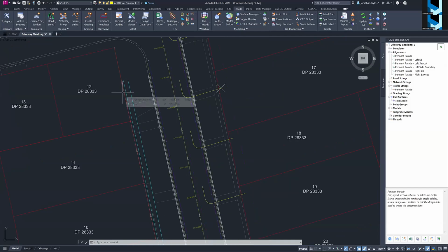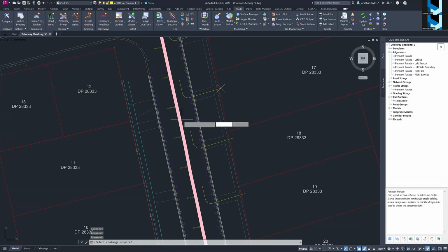As I mentioned earlier with regards to the design data form, we've put in a design variation, a custom variation, where we've matched the boundary code on this template to the natural surface. The custom variation called match to surface has the option of using a polyline to match to. Normally with the variation match to surface, you have to pick an alignment, whereas the custom one actually has the option of picking a polyline and then bringing with it the codes that are connected to it. So you end up with this quite awkward looking cross section, but this is the reality of this particular project.